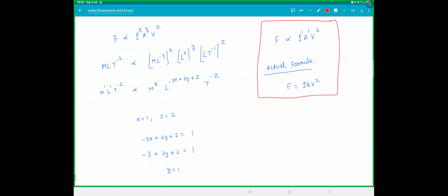And look at the formula there, F is rho A v square. That means if the speed of the water becomes double, you get 4 times the force. So this is the reason when there is a river flowing, and let's say in the river there are some stones, normally the stones won't move. But during a flood, when the speed of the river becomes 3 times, the force becomes 9 times. Getting it? So the stones which normally don't move will start moving during a flood because the force is proportional to v square.